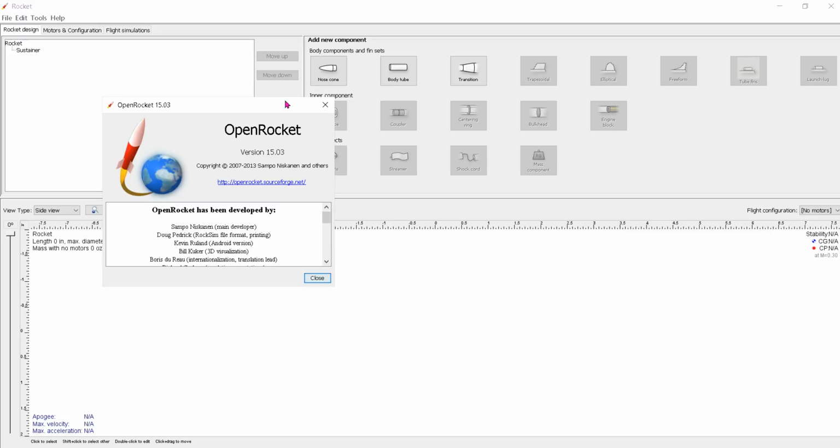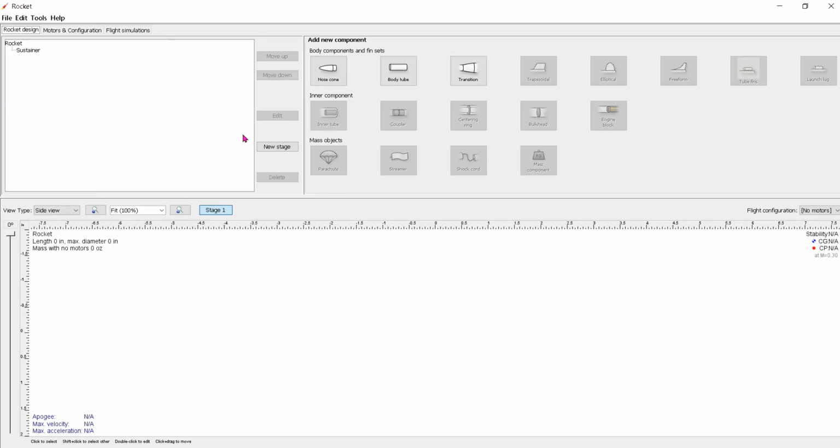The one thing you're going to notice about model rockets, there's pretty much three divisions. You got the regular model rockets, which pretty much any of us can do, keeps our cost point low. Once you get up to like E-size class motors, you're starting to get into what we call medium level. Once you get up to H and G, you're looking at what they call the high powered. In high powered, you have to be certified. You're talking much more speed, much more risk, things like electronics, altimeters, things that will pop out a drogue chute and then the main chute. There's a lot more going on when you get bigger and badder.